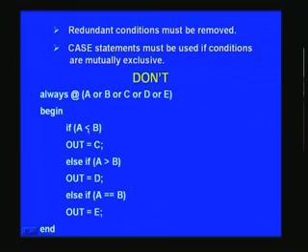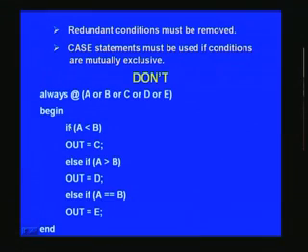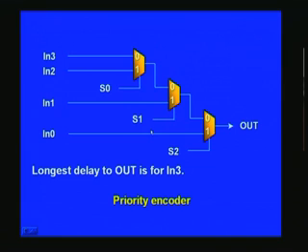So, I will tell you. See, if A less than B is not satisfied and it goes over here, then it implies that it is either equal to or greater. So, this statement takes care of the next possibility, and what is left is only equal to here. So, what is known? Why do you want to put another condition here which is already known? If you put this condition, what happens? It creates one more additional mux, as we have already seen. One mux for this if statement, then else if one more mux, and one more mux here, precisely the same thing as we had seen earlier.